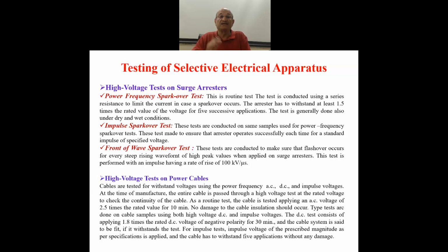After laying the power cables, DC tests are performed, as in general on any equipment after installation, after laying the cable, after installation of the transformer at site. It is always performed with DC, and that may require higher voltage than the AC magnitude, and also a longer duration of the voltage is applied in case of DC.